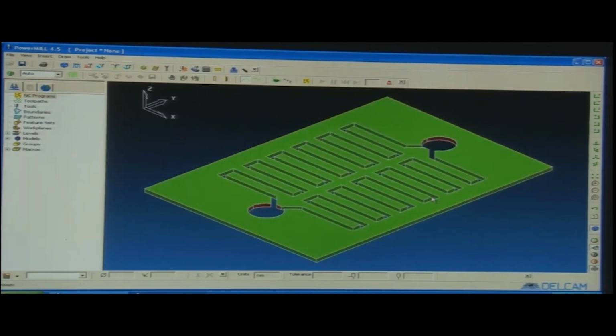Here we can see the different features or outlooks for the workpiece that we have. So, the software makes the task easy. It can create the code for all the points which are here. We can see that there is a circular profile, there is an angular profile here, there is a linear profile here. So, this is linear x, linear y. When the tool is going down, it is linear in z direction.